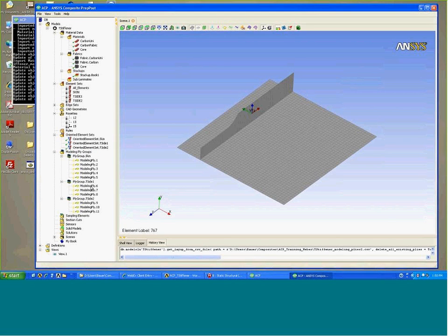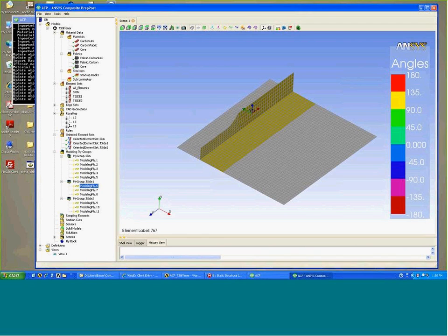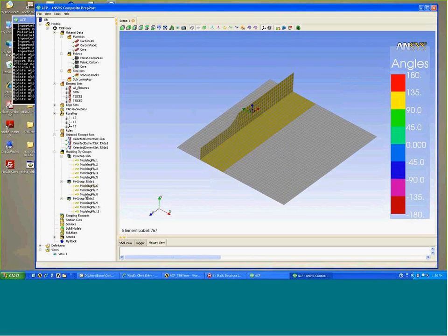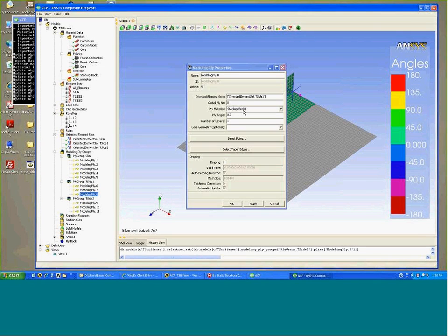So we can look at these. Just to double check our T-side definition, we have modeling ply here. In this definition, we used some unidirectional tape in the T-stiffener on both sides, but also for the modeling plies, we used our book Stackup. So each modeling ply here is identified as a single modeling ply, but we know from our stacking sequence this is actually 6 individual plies.